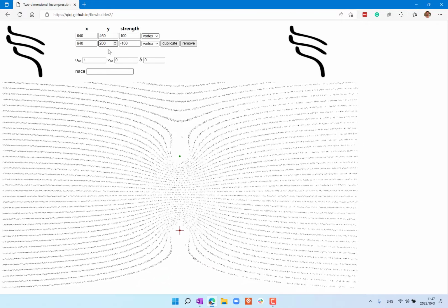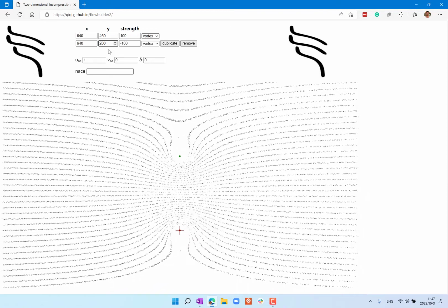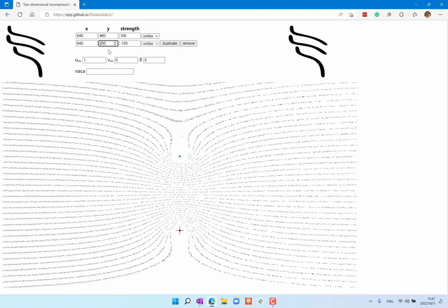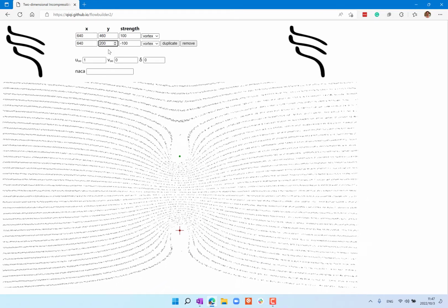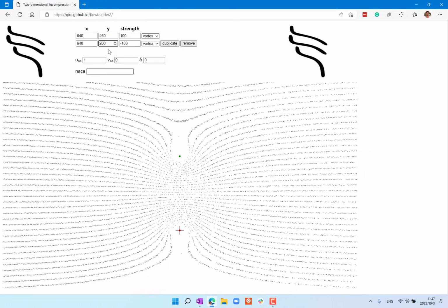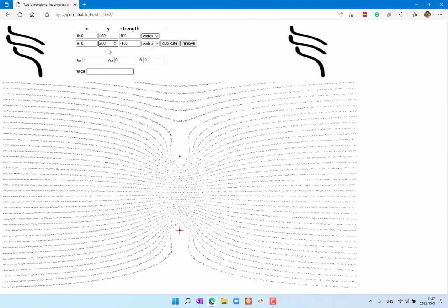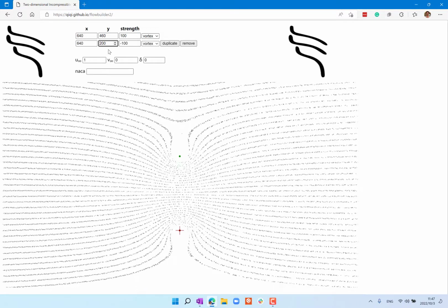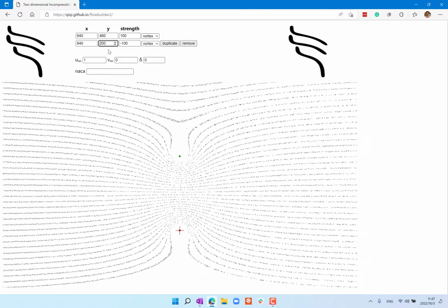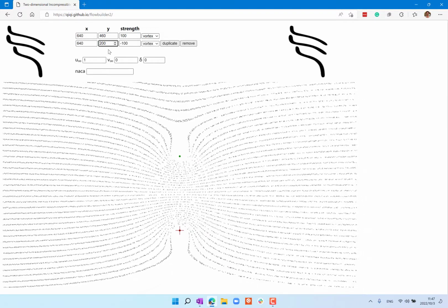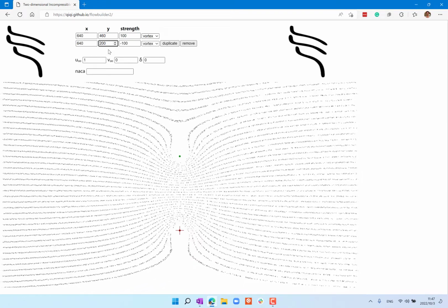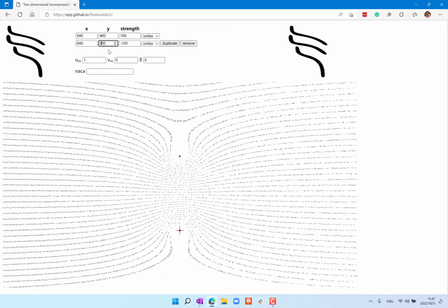Okay. Several ways to think about it. One way is to think mathematically, like what you just did. Remember the flow field around the vortex, right? How does the velocity depend on the radius? 1 over r, right? So the flow field in between is the summation of two 1 over r functions.